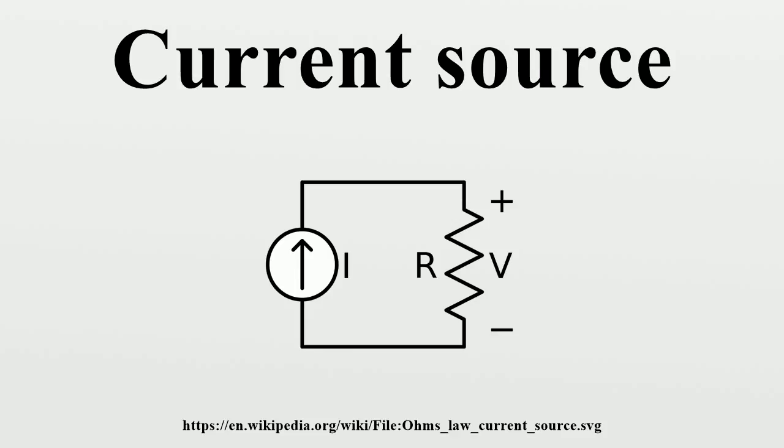The transistor Q1 adjusts the output current so as to keep the voltage drop across the constant emitter resistor R2 almost equal to the relatively constant voltage drop across the Zener diode DZ1. As a result, the output current is almost constant even if the load resistance and/or voltage vary. The operation of the circuit is considered in detail below.